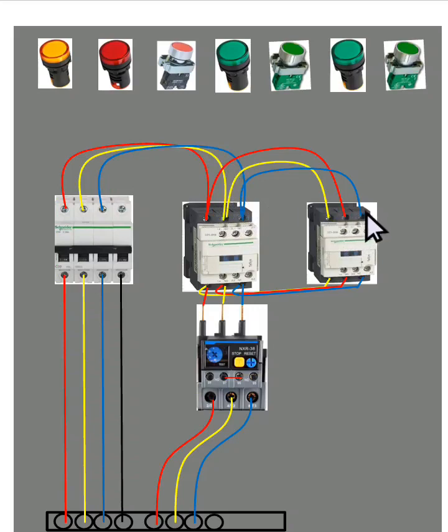If you want to move in the reverse direction, you activate this contactor. If you want to move in the forward direction, you activate this contactor. The outputs of the two contactors are looped together. The two contactors must not be on at the same time, or that will cause an explosion and possible damage to the motor, the load. The control diagram will show us how the two contactors are prevented from coming on at the same time.